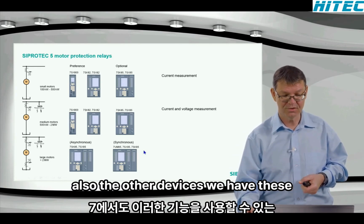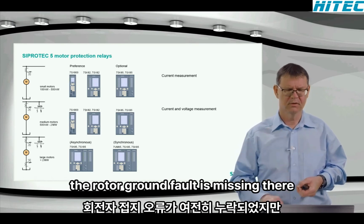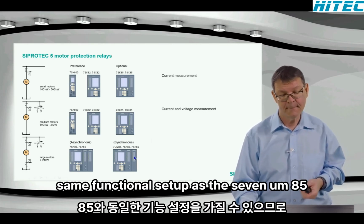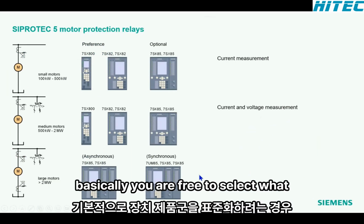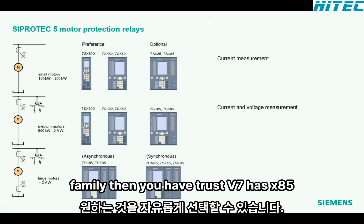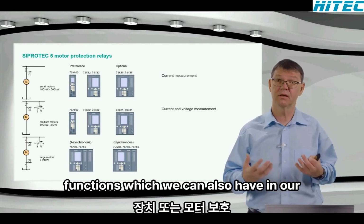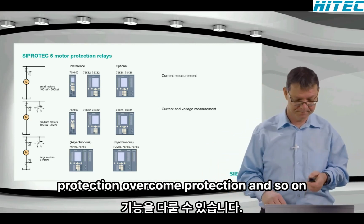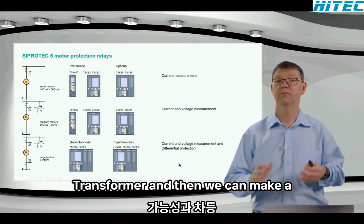Meanwhile, and therefore we added here also the other devices, we have these functions also available in the 7SK85. The rotor ground fault is missing there still, but in the 7SX85 I can have the same functional setup as the 7UM85. So also for the synchronous motors, we can choose one of these device types, and basically you're free to select what you want. SX maybe is interesting if you want to standardize your device family, then you have just the 7SX85, maybe a 7SX82. And with these devices, we can cover basically all protection functions, which we can also have in our family bound devices, so the motor protection, overcurrent protection, and so on. Okay, here additionally, the possibility to add more hardware for the second current transformer, and then we can make a differential protection.